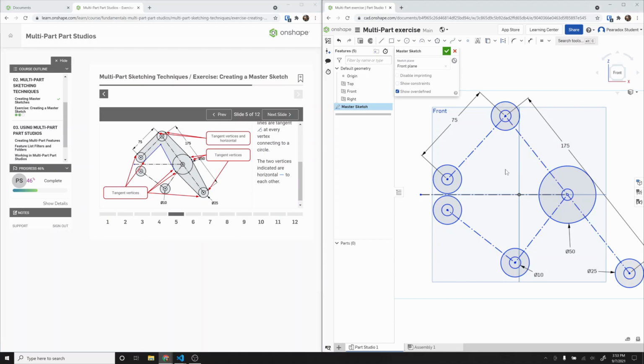We'll just hit L for the line over here, and I'm going to select here, and if you hover over it, you can see you can either make it coincident, or when you get to a certain point, it makes it tangent. So I'm going to make that tangent, and I'm going to hit escape because right now it's still trying to draw a line, and I don't want that. I'm just going to grab a point here and make this tangent. This just comes over here. It doesn't go anywhere in particular. This one needs to be tangent.